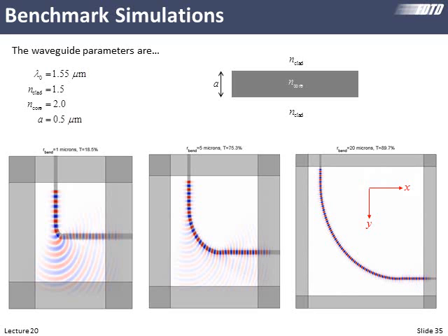So when the bend is 20 microns, we see that the transmission is about 90%. So 20 microns, that's huge. And this is a big problem in integrated optics, that these waveguide bends need to be huge so that we don't lose light. And there's actually been a lot of research looking at photonic crystal waveguides that can do very tight bends without losing power. So anyway, if you build this type of code, use these to benchmark yourself and see if you get these same types of numbers.